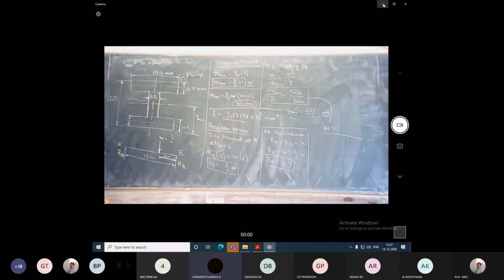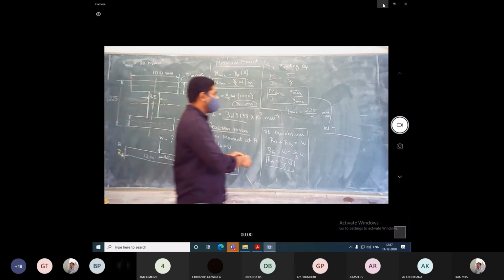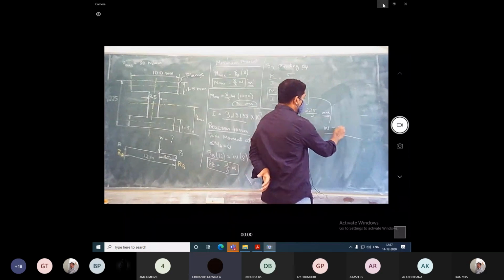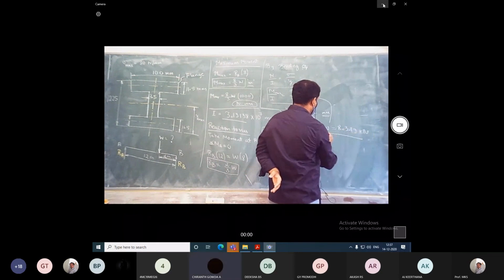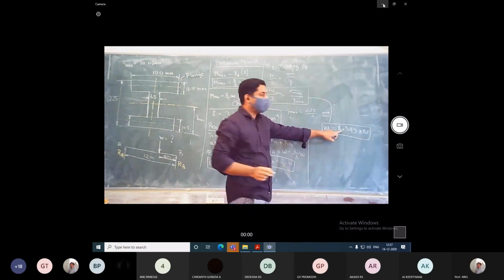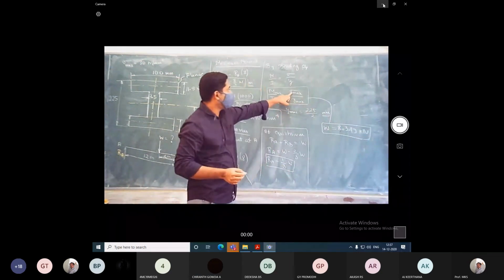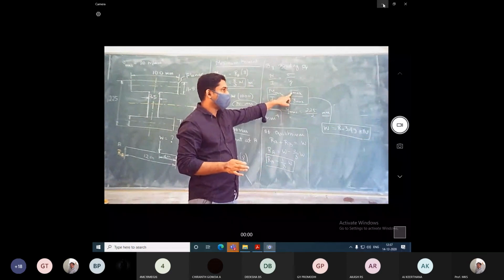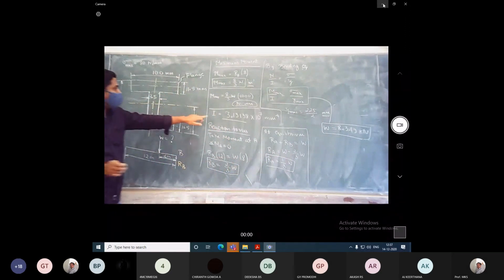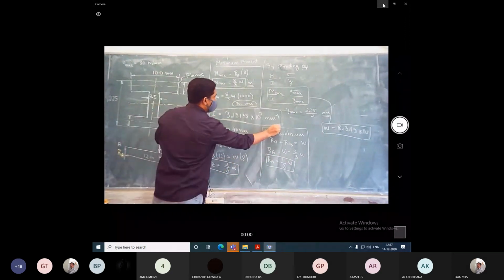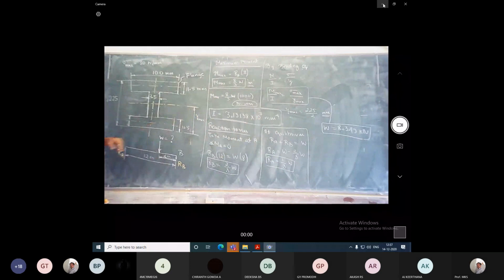Eight point three kilonewton. Just keep it to some three digits. So whenever you're keeping, 8.349 kilonewton. Okay. So in some problems they will give the load. If the load is given, we should be finding out sigma maximum, which will be unknown. Okay. So these are with respect to symmetric section. The only thing is how to calculate the moment of inertia. Other things are similar to the previous problem, what we solved in last class.